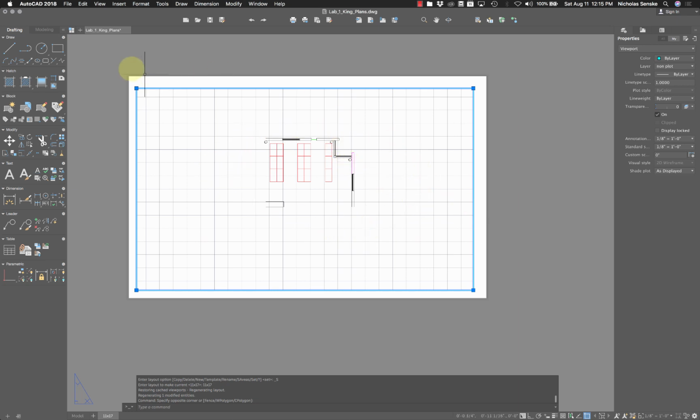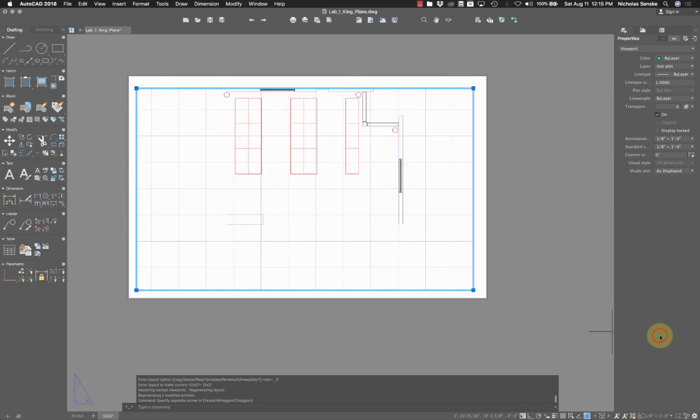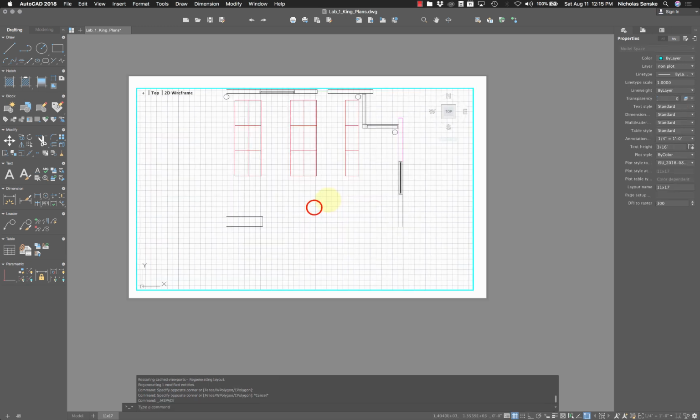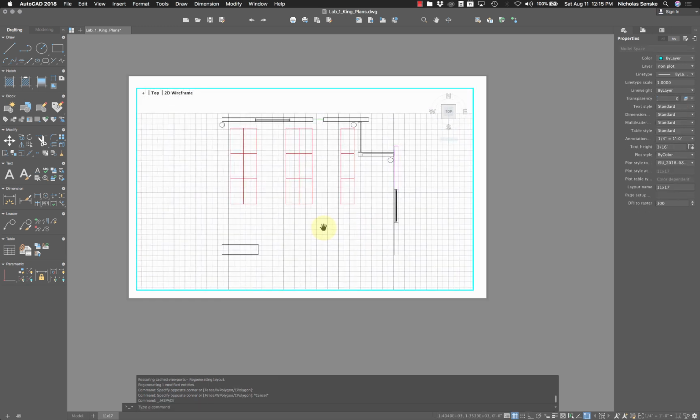And I could, right? Because I have this whole piece of paper. And that's what I'm asking you to do. So let's go up to quarter scale. That's starting to look a little bit better. I still have a lot of white space on the edges, but maybe that's where I put the scale. Maybe that's where I put the north arrow. I can start to see some detail in these windows a little bit, so that's pretty good. So you can say this maybe starts to be an appropriate level of detail for the scale in that drawing. So that's not too bad.